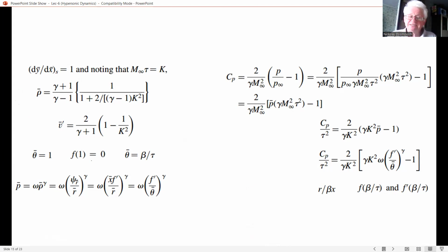In most practical cases, we are interested in the flow over a cone of specified angle theta sub c, or equivalently specified slenderness ratio tau, okay? And with a specified M infinity. Generally, for all our expressions, if we have a Mach number more than 8, all parameters are practically constant, no matter how much, 10, 12, 20, or more.